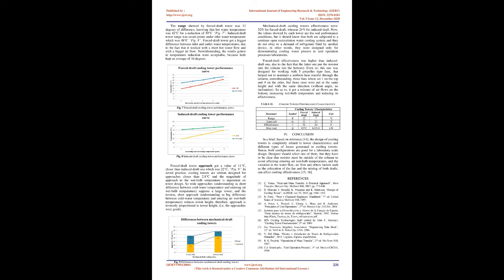Equation 3 is the effectiveness, in percent. Understand effectiveness as the thermal efficiency of the evaporation process; do not confuse it with the mechanical efficiency of the tower, which is relative to the energy required to let air circulate through the tower.